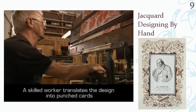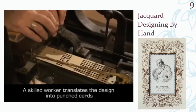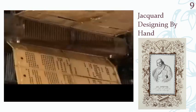Then this design was sent to the punching machine, where a punching person sits on the machine and reads from the left. For each box, he uses four fingers from the right hand and four fingers from the left hand, or maybe including thumbs, 10 from one hand and 10 from the other hand. He would be reading 8 to 10 boxes at a time, pressing for the box where he finds the filled color, and he does not punch when he finds it blank. He continues this by looking and visualizing the presence of a design there or not, and pressing the corresponding pins, and those pins are punching the holes accordingly. Somewhere it is blank and somewhere it is continuously punching.